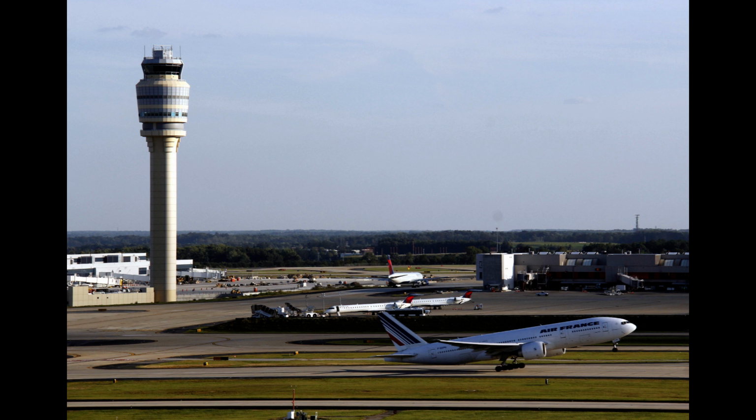A pre-departure clearance, PDC, program that allows pilots to receive a clearance via data link from a dispatcher or a data link communications service provider, e.g. ARINC, is available for Part 121 and 135 operators. A clearance is given to the dispatcher, who in turn relays it to the crew, enabling the crew to bypass communication with clearance delivery, thus reducing frequency congestion.